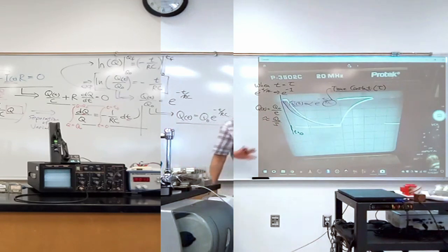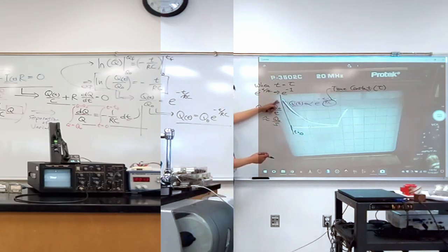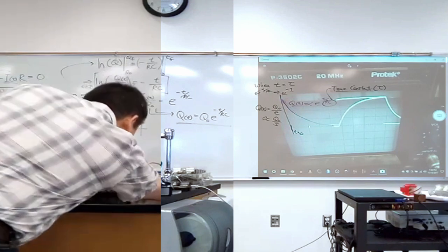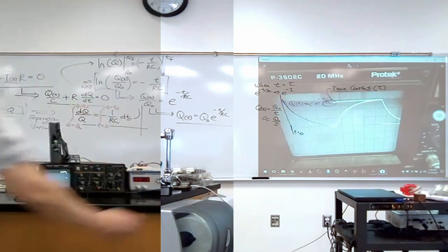So if you're trying to figure out the time constant on this graph, then what you do is look at how much the voltage falls to 1/3, or falls by 2/3. So it's starting at 1, 2, 3, and a little bit more divisions. Let me actually make it 3 divisions. I have control over my function generator. All right. It's almost 3 divisions now, right?